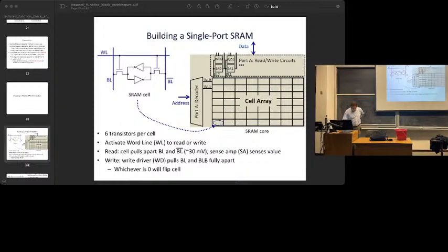Now this latch stays in its current state, and this side is going to be trying to pull this bit line down, because this inverter is driving out a logic 0. It's sinking current. And this side is going to be trying to pull this bit line up. So they pull the bit lines apart. And to make your SRAM fast, these cells are pretty small, right?